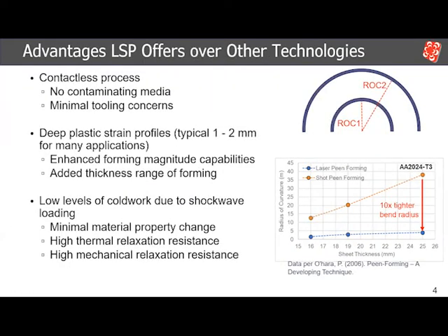As far as actual abilities of laser peening compared to some other technologies, the most comparable forming technology that we can look at is shot peen forming. And advantages that LSP forming offers over that, there's several. One of the first is that there's no contaminating media with laser peening, so we don't have to worry about shot getting stuck into any chambers within a part, or potentially transferring down the line into actually causing some FOD issues. As I mentioned earlier, there's minimal tooling that we have to work with, which makes this fairly simple to implement into a lot of applications.